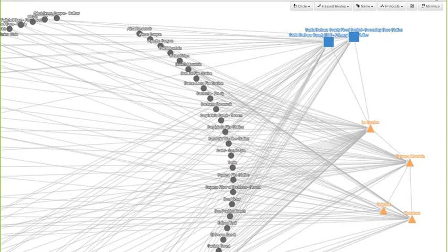So as you can see here, the gauges transmit to Twitchell and Plowshare, and actually they transmit to all of the repeaters. Each of these repeaters has gauges that it listens to directly, and the base stations also listen to a few gauges directly. The gauges that are heard by Twitchell and Plowshare are then repeated to Figueroa Mountain. Figueroa Mountain transmits to LaCumbra, and LaCumbra transmits into the base stations. If they had just alert gauges, we could plot those on here as well. We can grab an image of this if we want to share it with anyone.